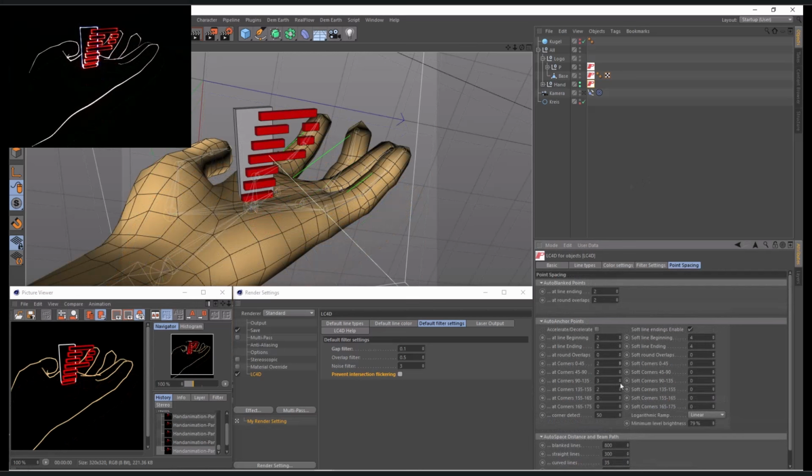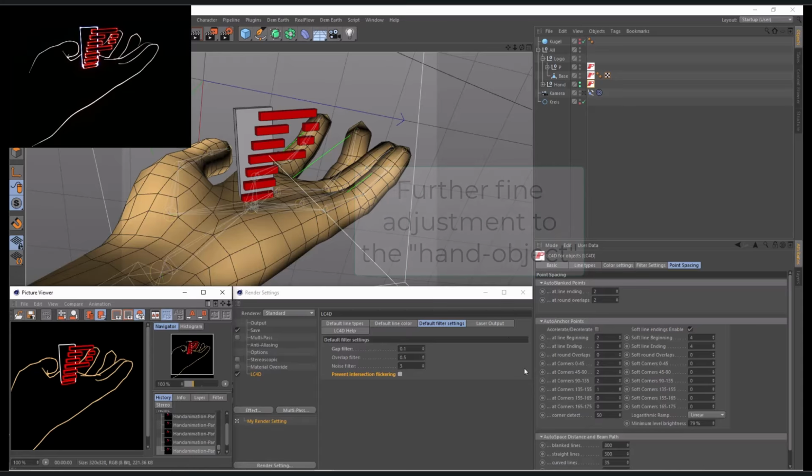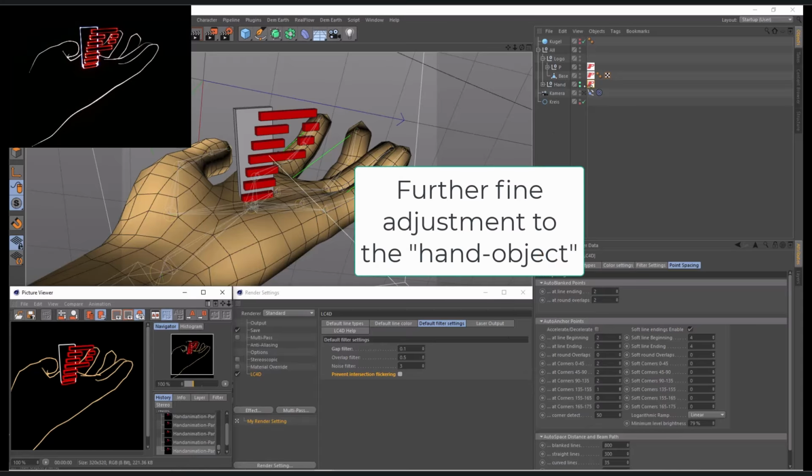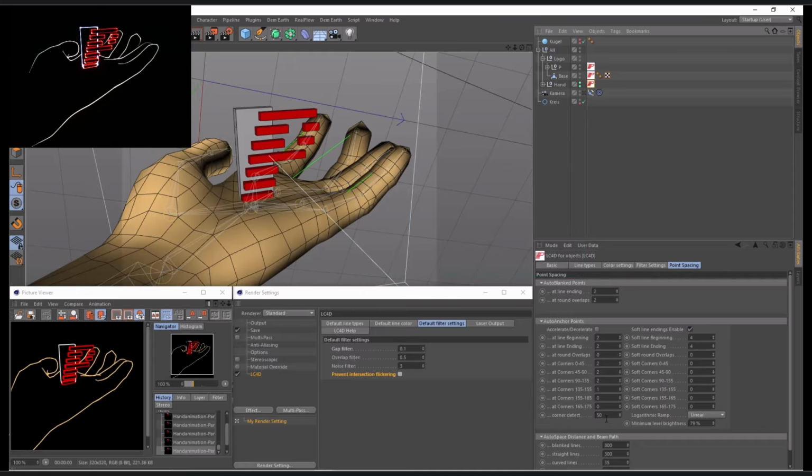With all those angle interpolation settings, there won't be any clear recommendation, but you can simply play around and try several settings step by step, since this strongly depends on the frame you're working with. In my case, one helpful setting will be the corner detection of the hand object, since the hand is mainly showing only round shapes without real corners. This means this value can be reduced, since I don't expect any sharp corners in this object. Only for the hand, of course.